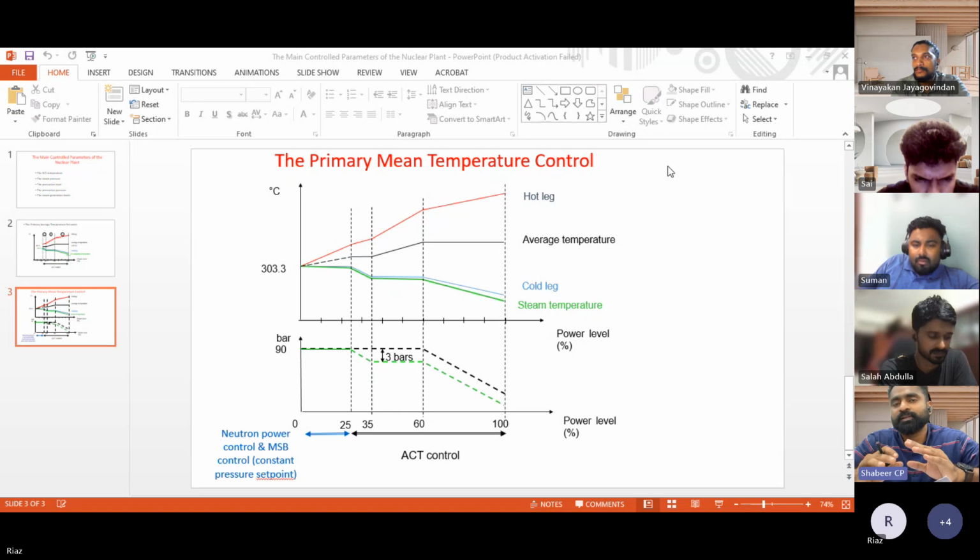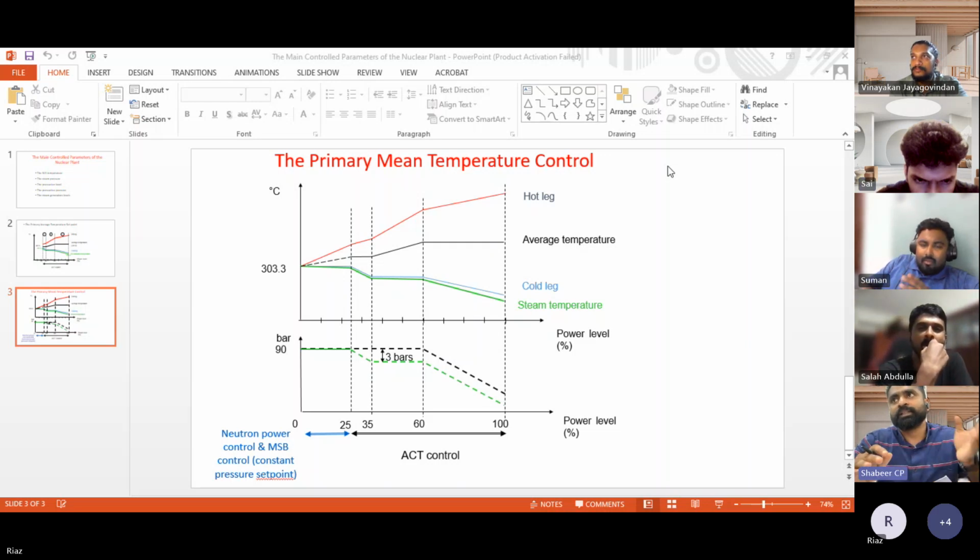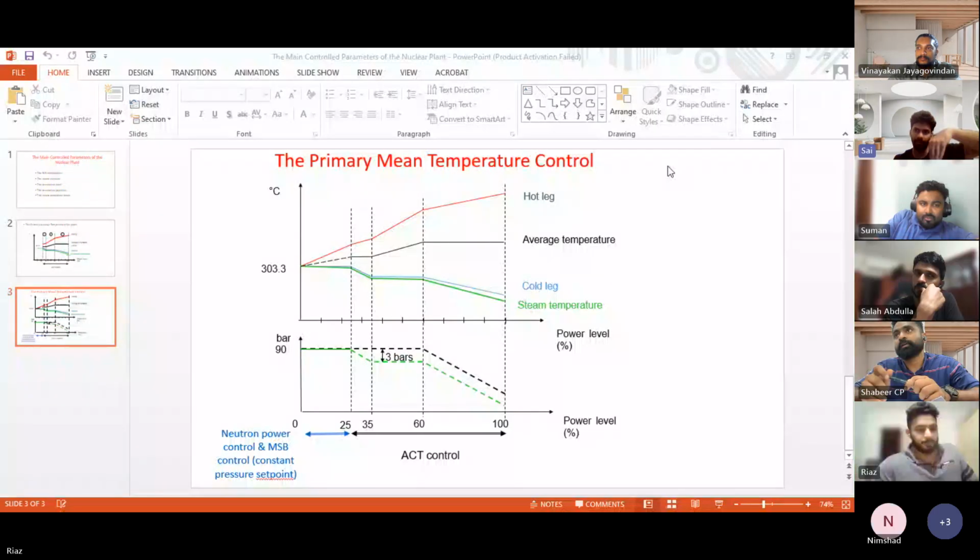If the load demand is reduced, the required electrical generation is reduced. But the heat generated in the steam generator still produces steam, while the required electrical energy is reduced. At that time, we have to bypass the excess steam. It runs continuously as per the requirement, and power may vary.